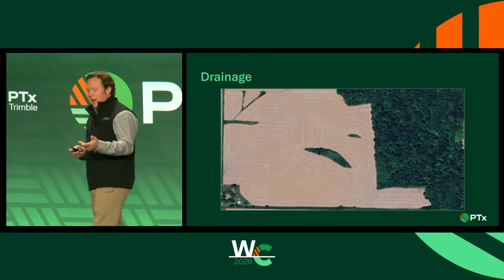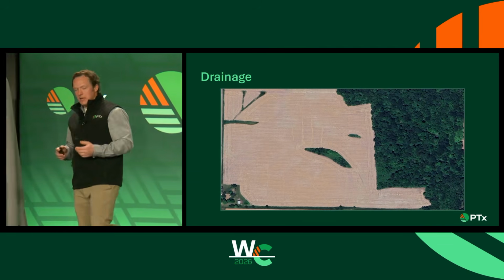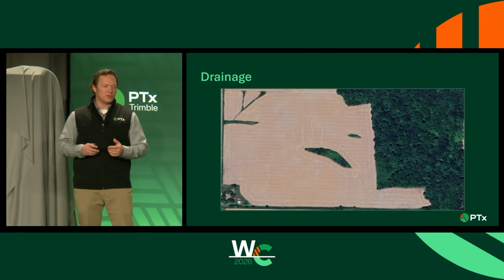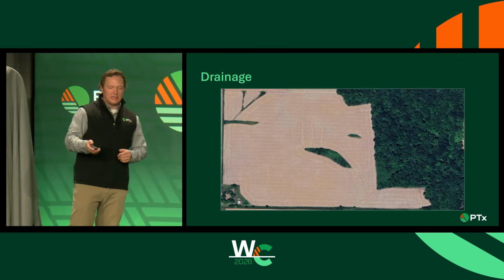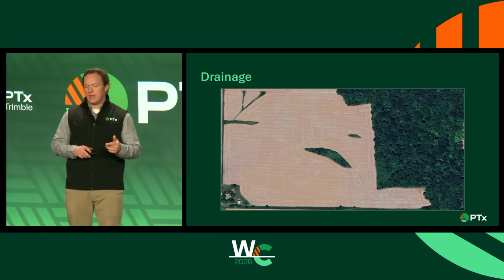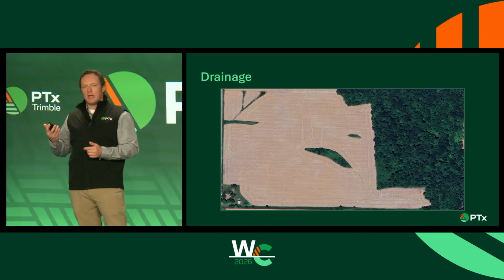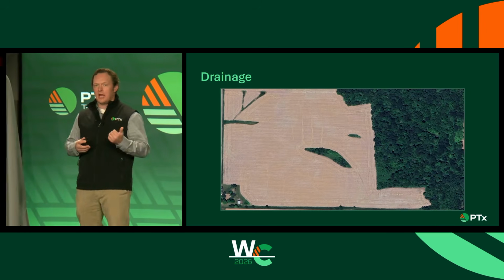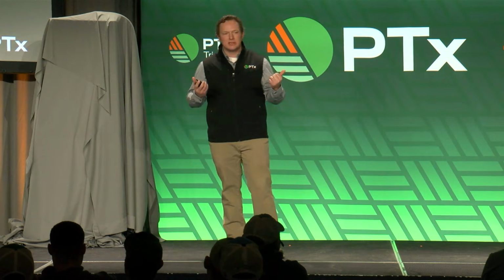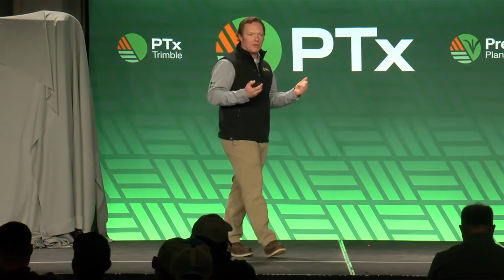And so what I want to actually talk through is what we have done on this farm from a drainage standpoint over the last year. How do we shorten this learning curve? In this particular case, I did know there was a little bit of tile in the farm. When I had looked at it, I had found an outlet back in the timber, and I had also found a big tile hole up by the road. So I knew there was water draining both directions. I just didn't know where the tile was or how much was there.